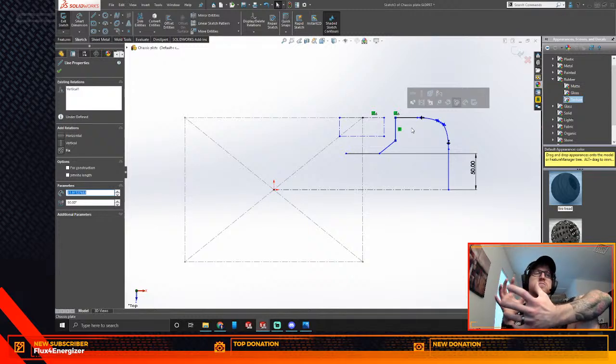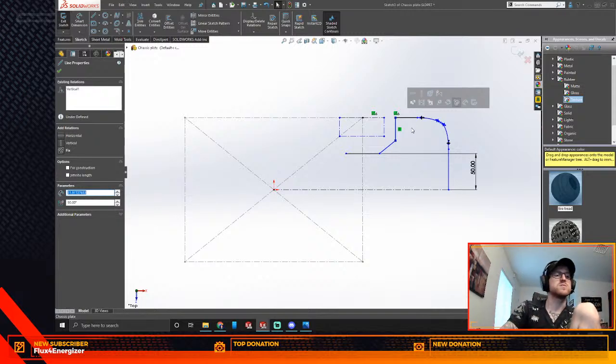We can make that as low as possible. But one big drawback is it's going to add unsprung weight. And we want to help mitigate unsprung weight. So that means that we would have to have the wheel well be kind of like this bean shape so that the tire can go back and forth and not have to rub.